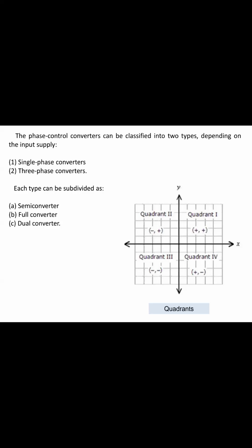So a thyristor may be forward biased, but it stays in the off state. When I give the pulses, the thyristor is turned on, and then the conversion process takes place. So that is a fully controlled rectifier, using thyristors.